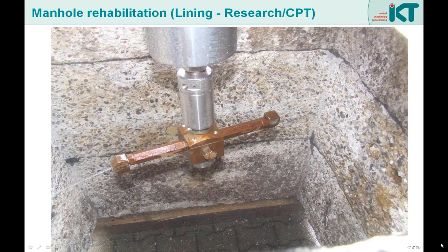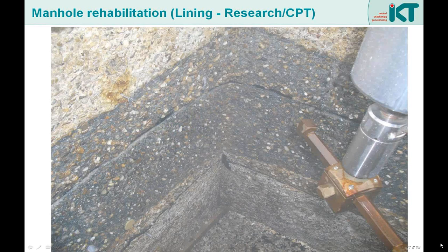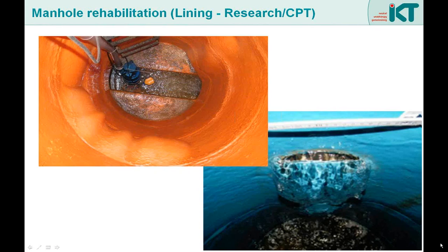Here we can see the surface of a corroded manhole before preparation. And here, after applying the device. We tested the surface stability by pull-out tests, and the results were quite assuring. The value of tensile strength was comparable to new concrete.